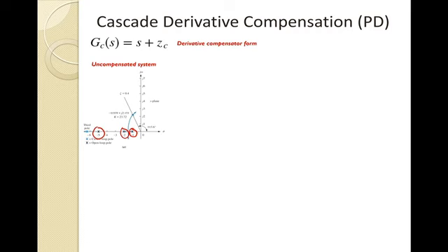Now, depending on the value of K we desire here, if we wanted a certain damping, in this case 0.4, what we did is we swept and we got a value of K here of 23.72, and then we could factor, find the roots here in the denominator of the closed loop transfer function for that value of K, and then what we'll find are we have these dominant poles here, the closed loop poles. You're going to see a third pole right here just to the left of -6, and then the two poles right here at minus 0.939 plus or minus J 2.151 for that value of K.